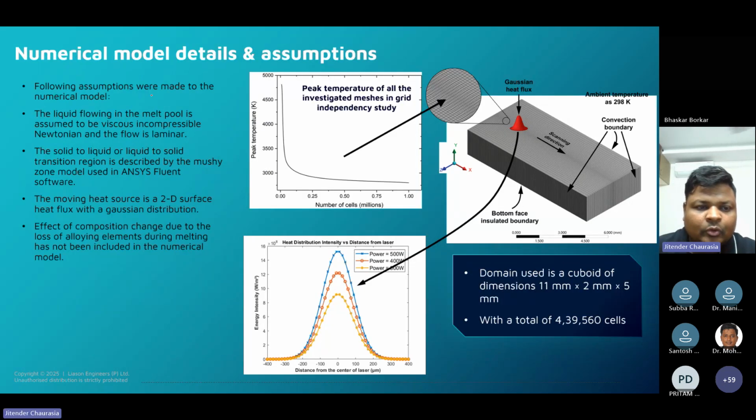Before I did this on ANSYS Fluent, as I told, I did a grid independence study. So how many cells to have here. As I remember, I used this point because from here to here there was hardly any difference, like 3% or 4%. If I count time, if the simulation takes around 30 hours here, here it takes almost 70 hours or so. So result wise, there is only 2 to 3% difference, but time wise, it's more than double. So I stuck here, I remember.